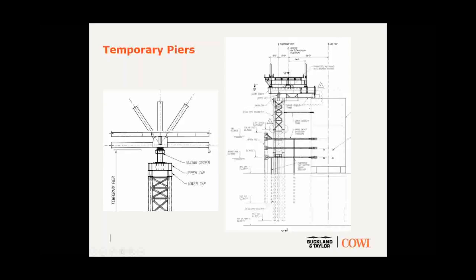To the left of this picture, you can see in elevation view the top of the temporary tower and the little grillage that gets it focused on the panel point where the bearing is and where all the load comes down. It's worth mentioning that the load that's transmitted from the sliding girder during full design load during the temporary usage of the bridge coming through this point onto the top of this grillage and temporary tower is on the order of 11,000 kips. Pretty big load.